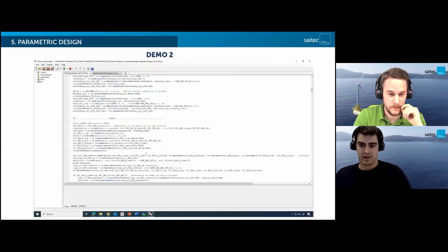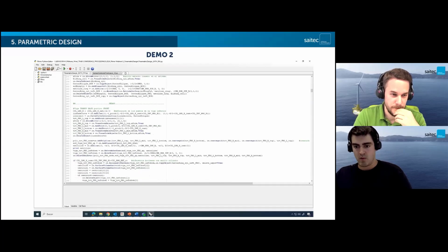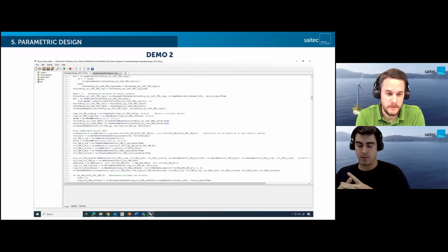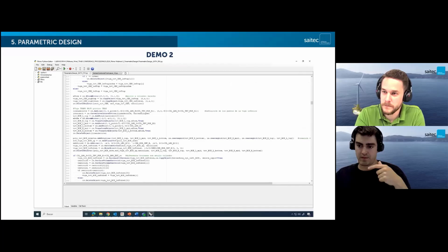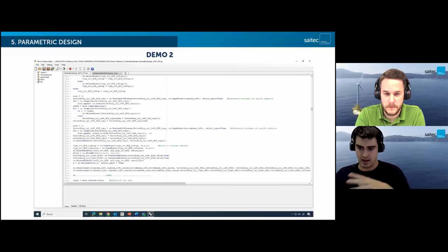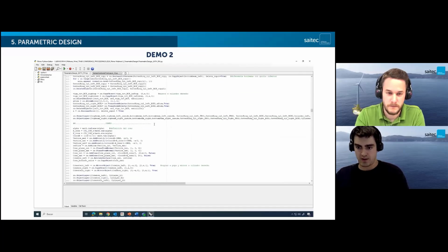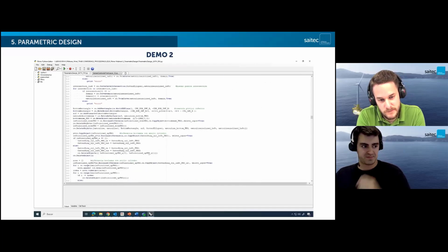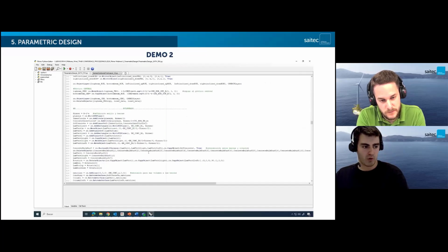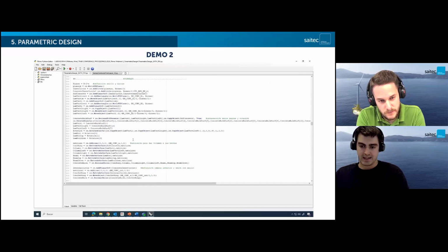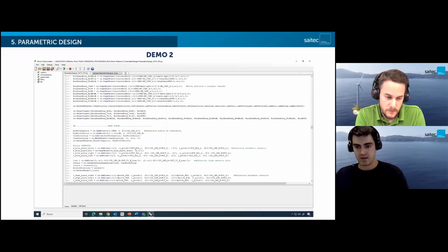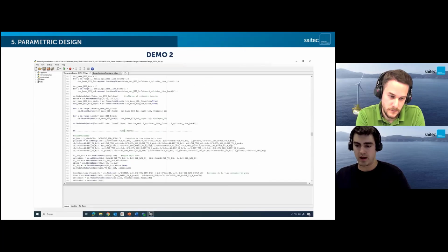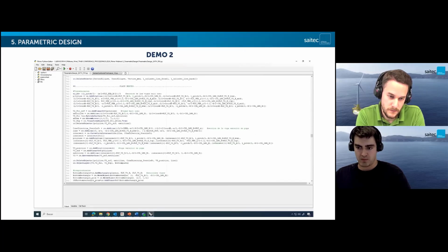Then we define the cylinders. Then we move to the beams. So usually our common process is to define first the curve, then the surface and extrude, constructing the polysurface. So then we have the cones, the cylinder gantries. We also have the bulkheads, the heave plate. Then for the heave plate, we also define the nerves of the plate, the connection beams.